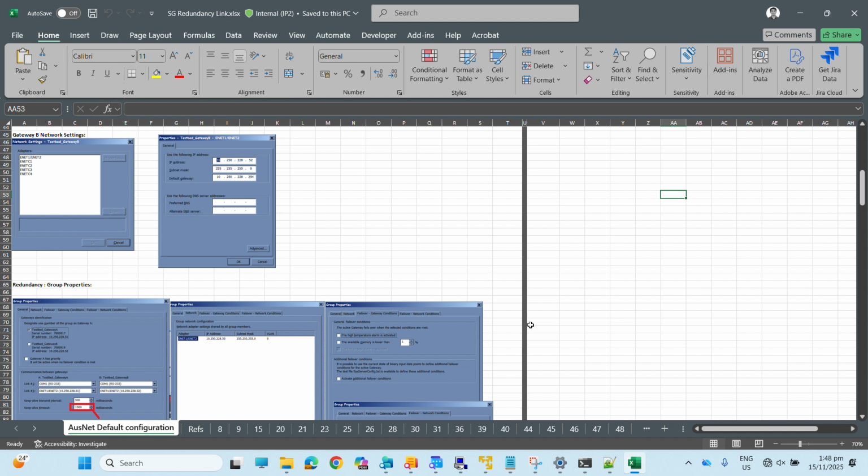If they were already online, the best practice is, say you made the config for that single file, do that first on the standby, not on the active one. Once you send that to the standby and it already has the new latest config, send that to the active one. Then when the changeover happens, the system will already get the new config file from this standby. So that's the best practice, rather than putting it first on the active. Just do it to the standby first.